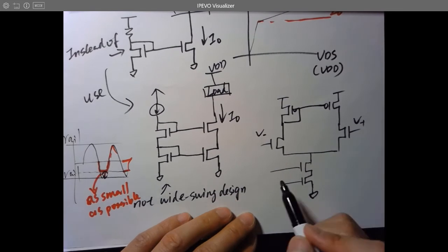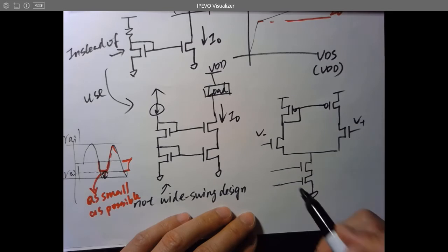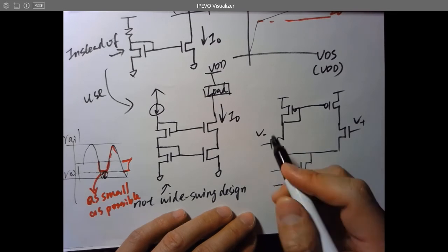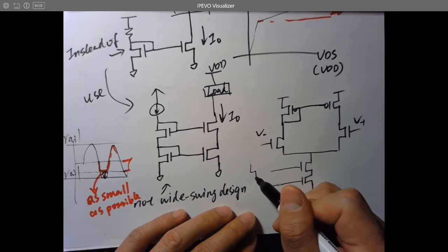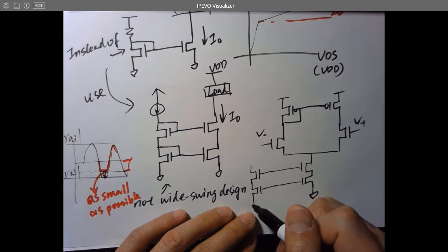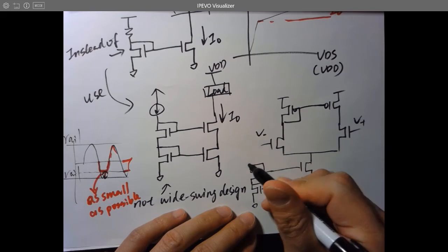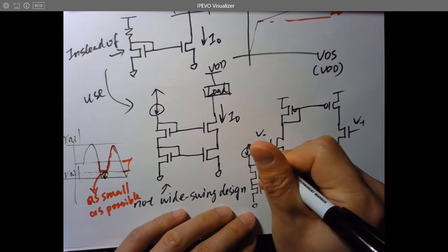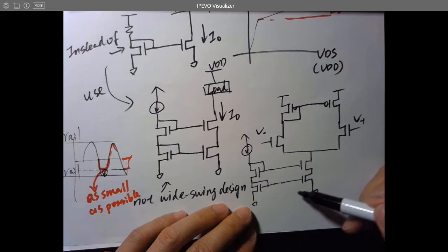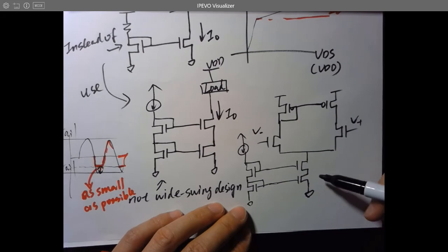And we want to bias, we have to pass the VGS to this output stage. So you need these guys to do this job. All right, and here's the original current source to bias your 2 NMOS cascoding current mirror over here.